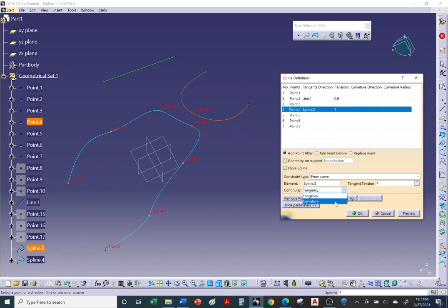If you don't see curvature on your CATIA at work or at home, or maybe it's grayed out, chances are you have the basic license and not the advanced license for generative shape design. So watch what happens when I click on curvature in 3, 2, 1. See how it gives it more shape? It's trying to clean up the curvature. Okay, so we have curvature.